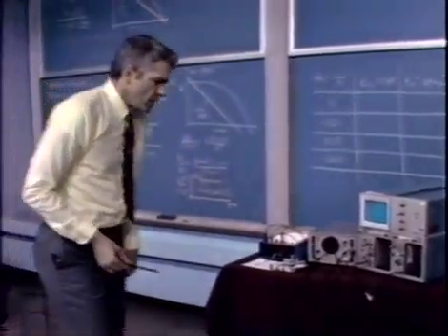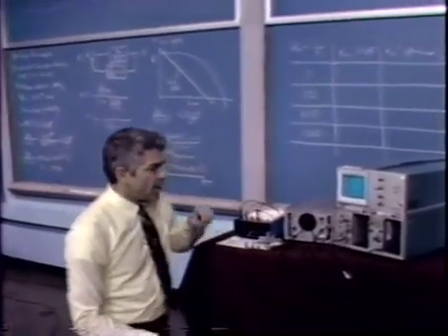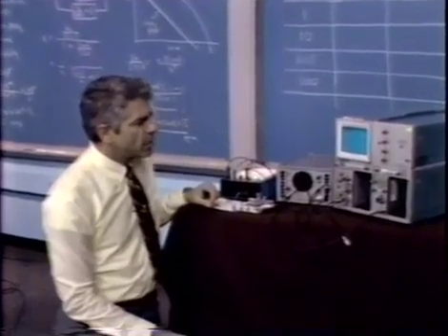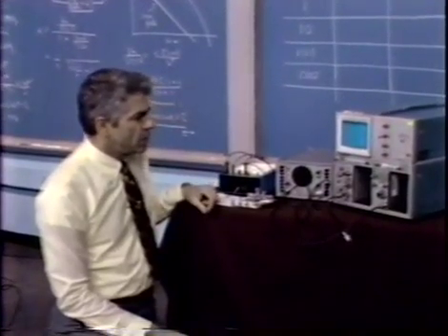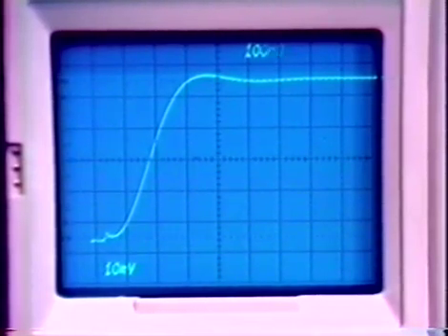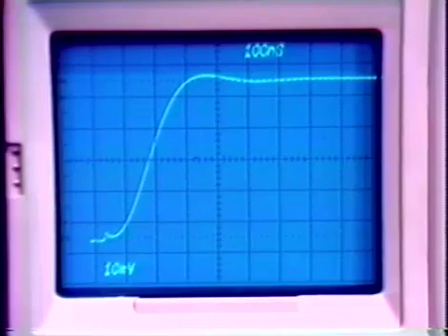With this particular amplifier, we found that we get very nice stable responses with just a small amount of overshoot, as presently shown on the oscilloscope, in unity feedback configurations when we use a 20 picofarad capacitor. Also, if we look at the transconductance of this amplifier, we find it's a little bit higher than the nominal value. The unity gain frequency with a 20 picofarad capacitor is actually about 2 megahertz in this particular amplifier.